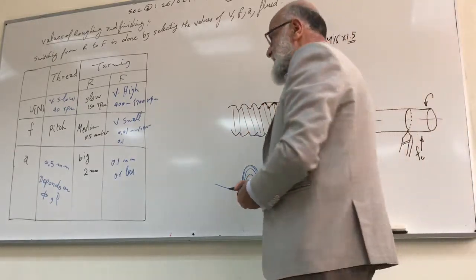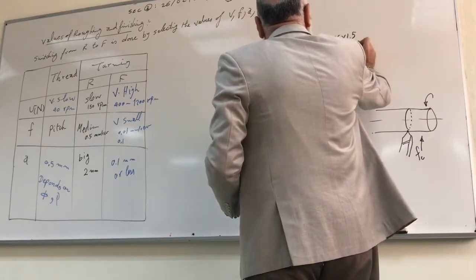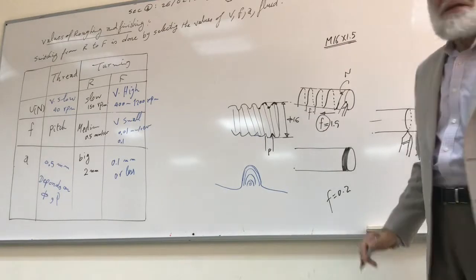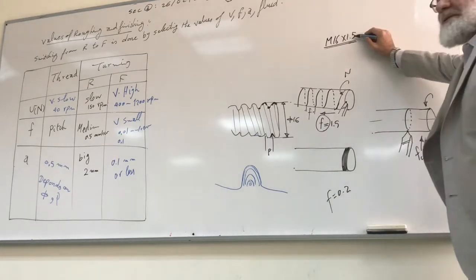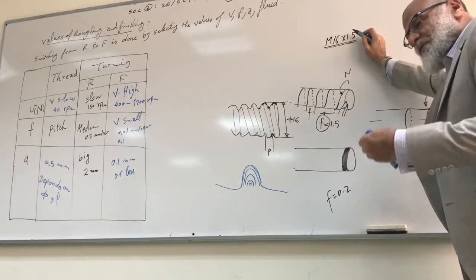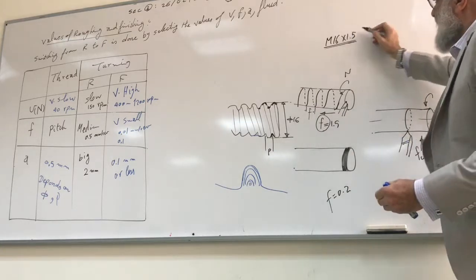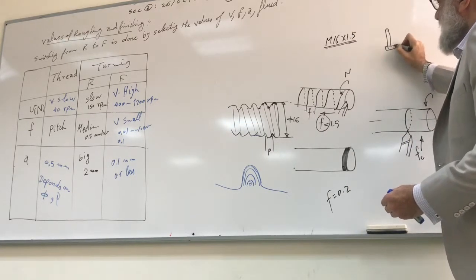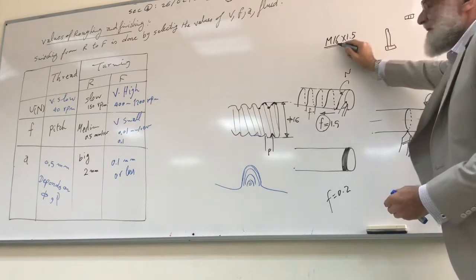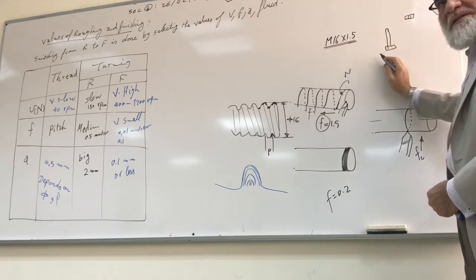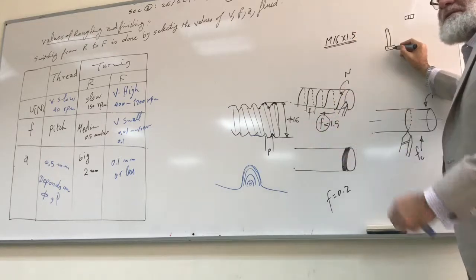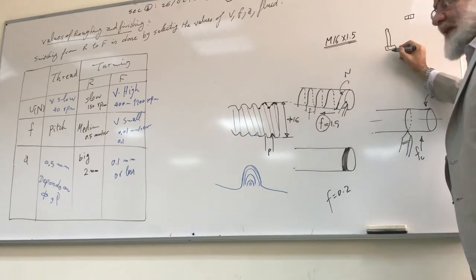For example, do you know this title or this name, what does it mean? It means standard bolt and standard nut. Also, what is the meaning of standard bolt? What's the meaning of standard nut? If the bolt is manufactured in Japan and the nut in Germany, and this is M16 1.5 and that one is 16 1.5, I will take this, mount it here, and it will go on easily. Okay? This is the meaning.